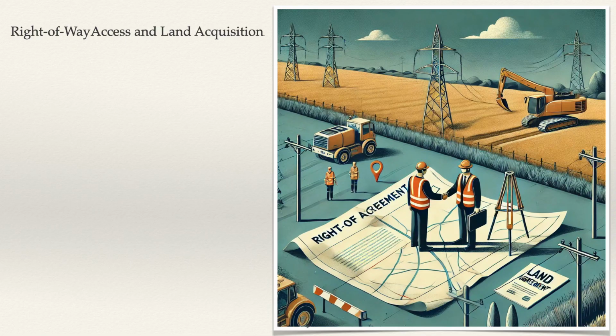E. Compensation and landowner agreements. The project team provides fair compensation to landowners in exchange for ROW access. These agreements are documented legally, outlining terms, compensation details, and ROW usage conditions. F. Legal documentation and ROW management. All ROW agreements are documented and legally recorded. The contractor also manages ROW upkeep, including clearing vegetation, monitoring erosion, and ensuring safe conditions along the transmission line route.